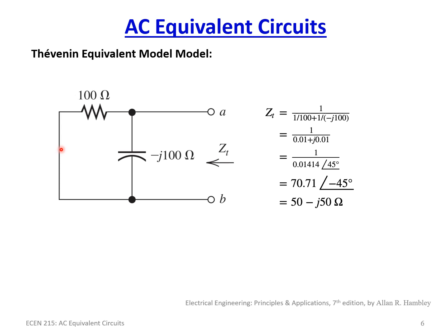I find it easier to do the zeroing method when there are a bunch of independent sources, and we have two of them in this case. Just a reminder, for the zeroing method, a voltage source becomes a short, and a current source becomes an open. It's as simple as that. We had a voltage source located right here, and it became a short. And we had a current source located right here, and it became an open.